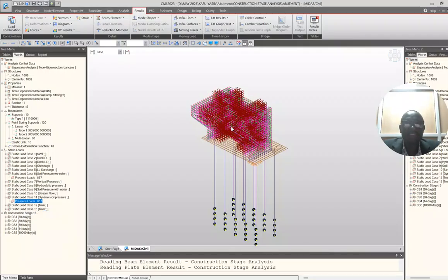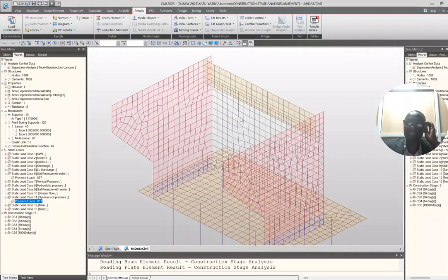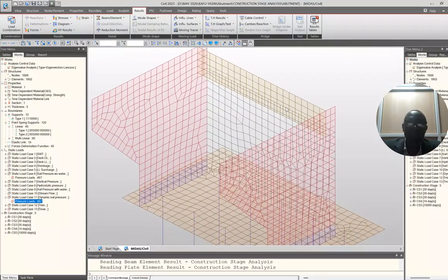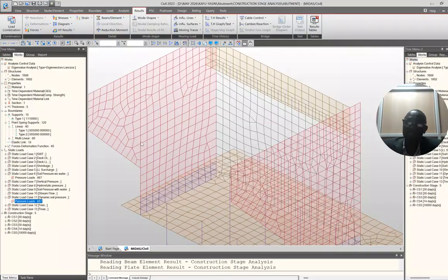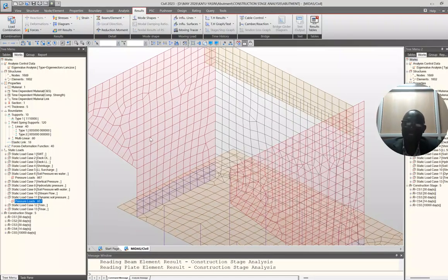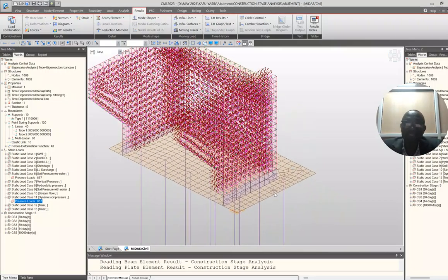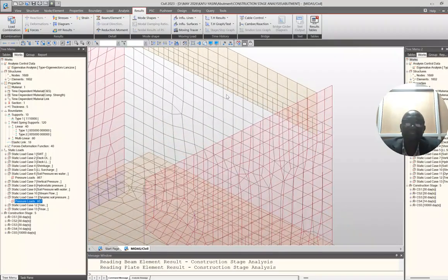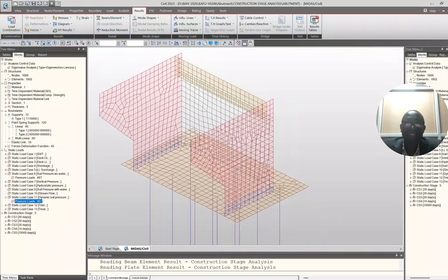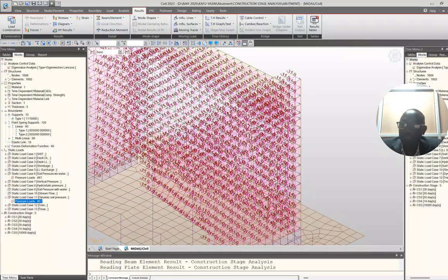from seismic. Recently, we had a seismic tremor here in Uganda with epicenter around Nakasongola, and the PGA was about 0.02 with a magnitude of about 4.5. Definitely, of course, we shall get a better result from the Department of Geology and Mines, so that we understand that. But normally in our design, we consider a PGA of about 0.03 in the central region, because our active faults lie along the western axis, western region, and eastern.